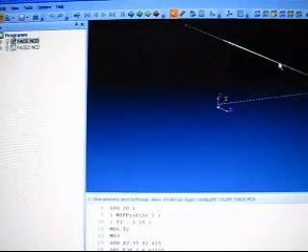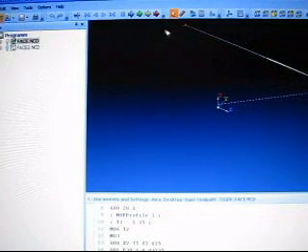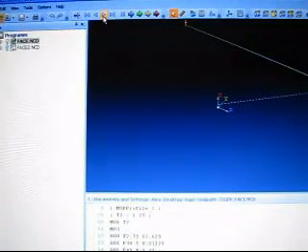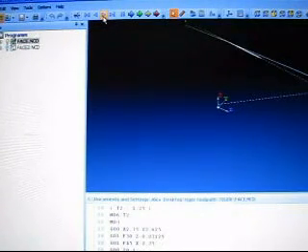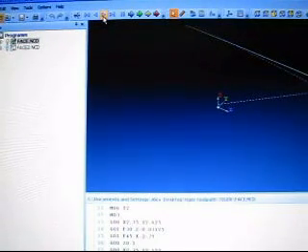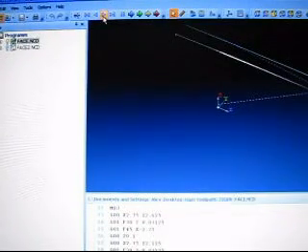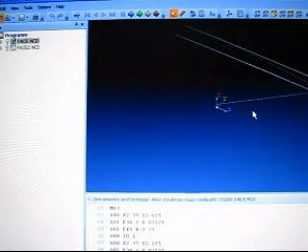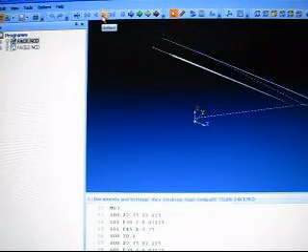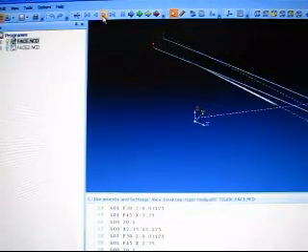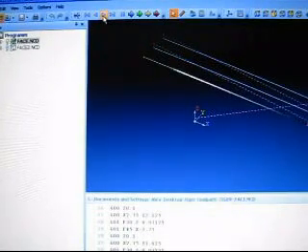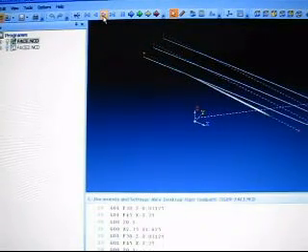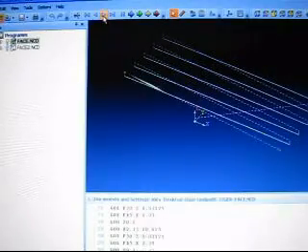It's going to enter the part in a milling fashion, not plunging, milling side to side. Then it's going to mill this conventionally, step up off the part, come back, plunge down, not into the part but off the part, and then proceed with another milling cut, which is conventional. Then it's going to come up and back, come down and cut, come up and back, and it's just going to keep repeating this.